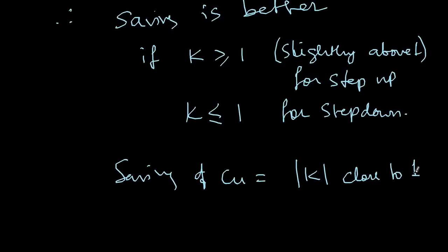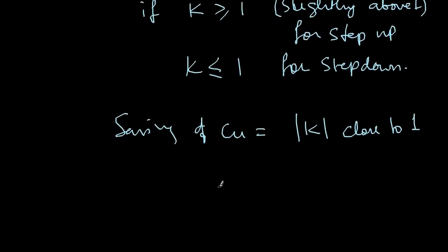So therefore we don't find people using auto transformer for, let's say, major generators, where let's say 13 kV is generated and I want to step up to 132 kV. So almost a factor of 10. So for 1 is to 10, it is better to have a two winding transformer. You will have electrical isolation and there are other benefits that way. Whereas if there is a slight variation in the voltages and the transformer ratio is close to 1, then we prefer auto transformer.